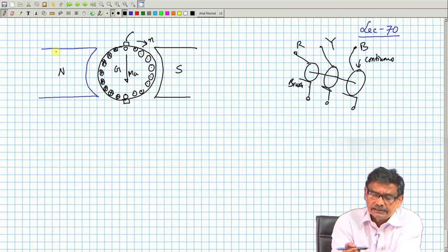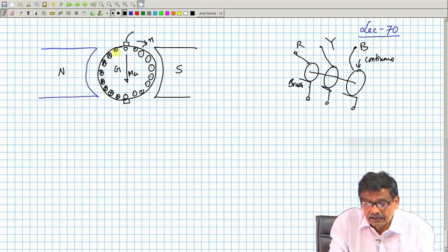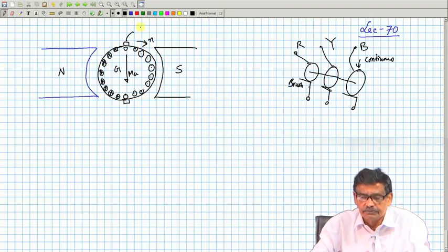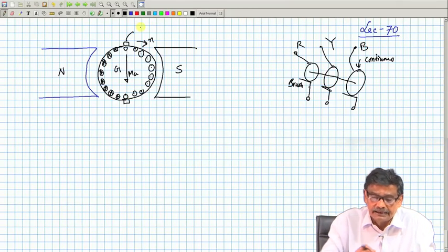So, that is why the rotor terminals in a DC machine are accessed by commutator segments and brushes, to make it DC. Also, when a particular coil comes to this position, only then these two ends get connected to the brushes, and different coils come at different times. That is why, in space, whichever coil comes to that particular position gets connected through the brushes.